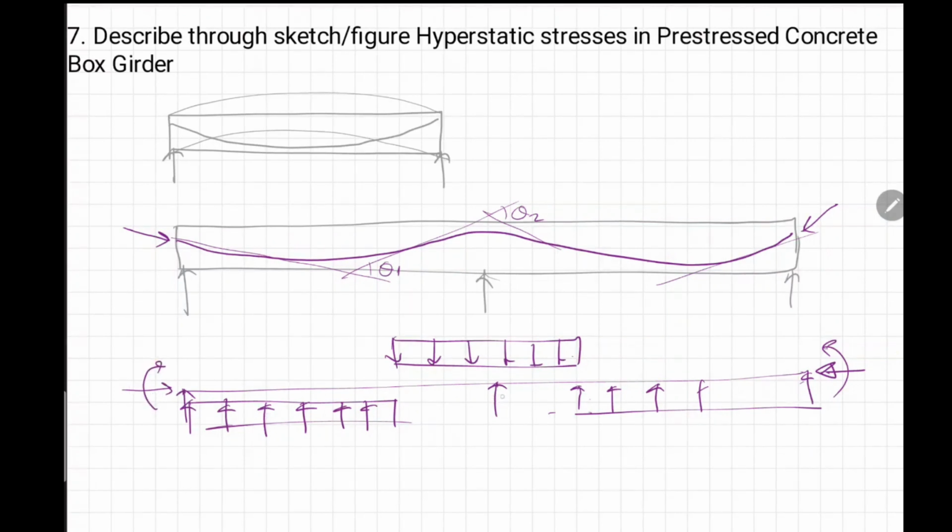Since it is a continuous structure, this will generate stresses, and the stresses generated due to restraint and pre-stressing force are called hyperstatic stresses. So this happens only in the case of indeterminate structures.